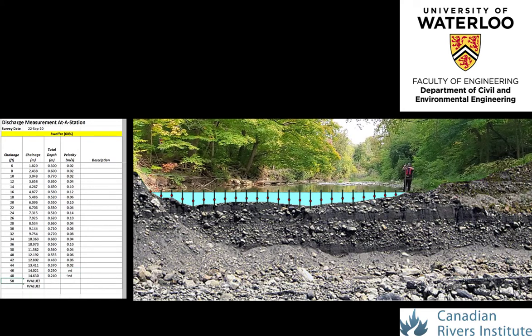We see as the field hydrologist nears the right bank of the channel, the flow depths become very shallow. Here at the 50-foot location, the flow depth is just under 2 centimeters and the flow meter is not fully submerged in the water column. Here the flow velocity is recorded with the code TS, indicating that there was insufficient flow depth present to obtain a measurement.